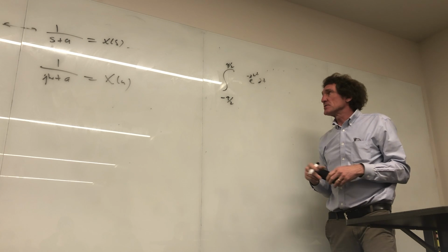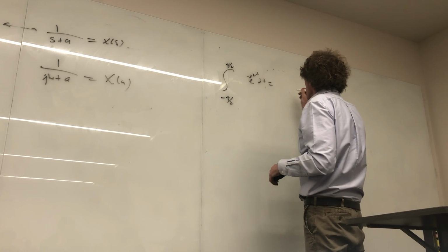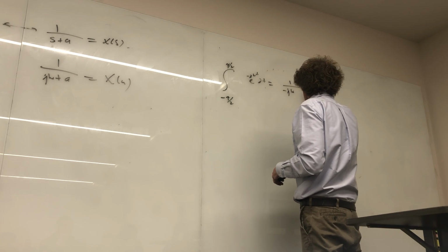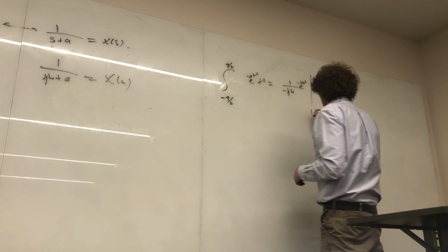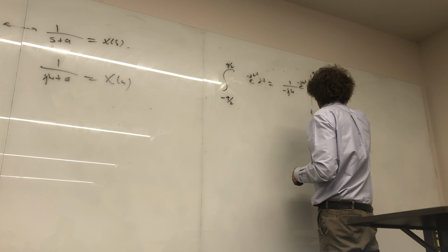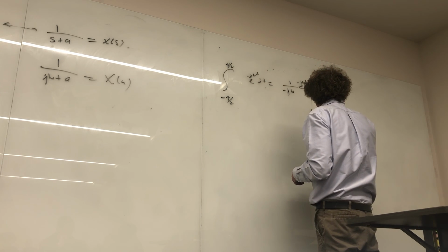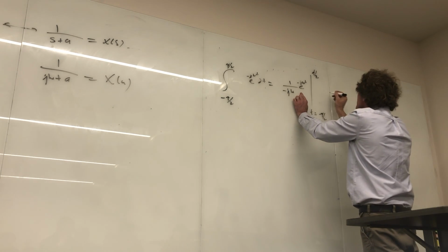All right, do the integration with me, and I'll show you a couple things. Now, when I do this integral, what do I get? 1 over minus j omega, times e to the minus j omega t, where t goes from minus tau over 2 to tau over 2. Y'all agree with that? All right, let's go ahead and do that.